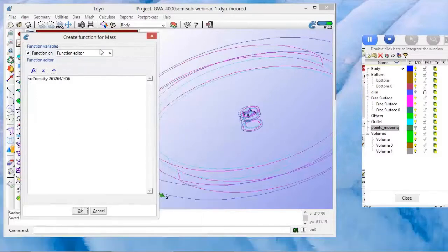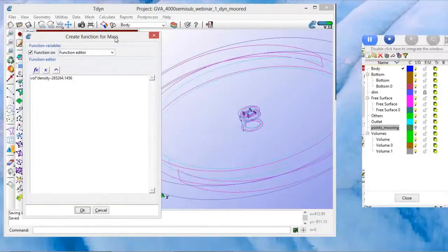Well, you can imagine it's in an Excel file. You just get the length of the moorings and their specific weight, and you just calculate the whole mooring system weight and subtract it from the displacement. In this case, because we want the floating line to remain in the same position as in the previous model.